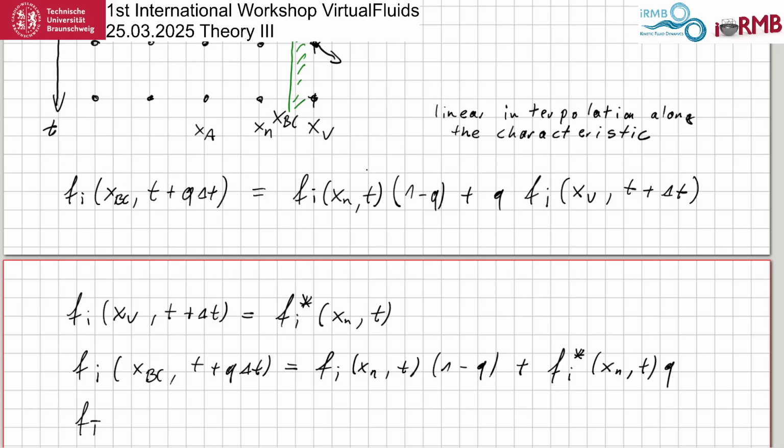So you also want to have sometimes velocity boundary conditions that are not aligned with any grid. For example, if you have a moving tire or a moving plate, okay, so you're wind engineers, if you have a moving plate somewhere, so you want to have a non-zero velocity boundary condition that is cutting through the domain.